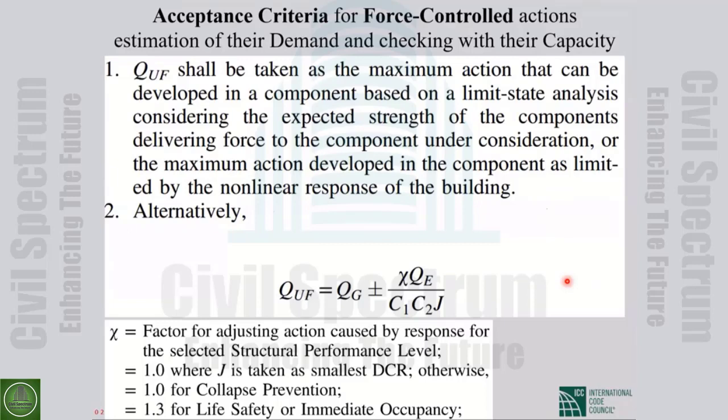Now, what is the problem with force control actions? What adjustment should we do for the force control actions in linear analysis? Two modifications should be done. One modification is that we increase the base shear by C1, C2, to have the maximum displacement as in reality. But now we don't concern ourselves about displacement; we are concerned about forces.